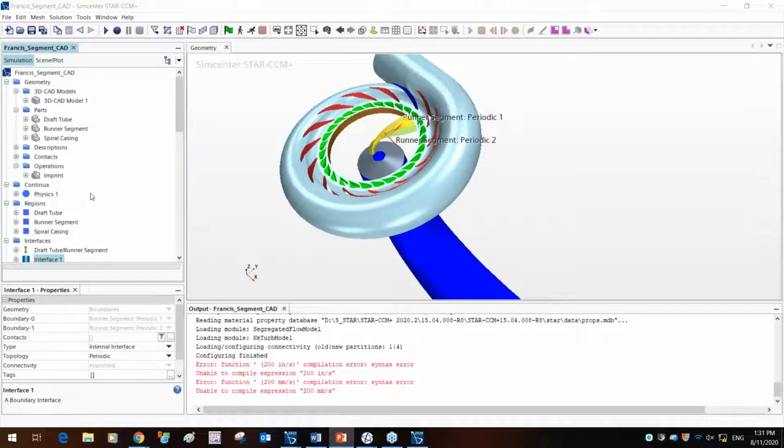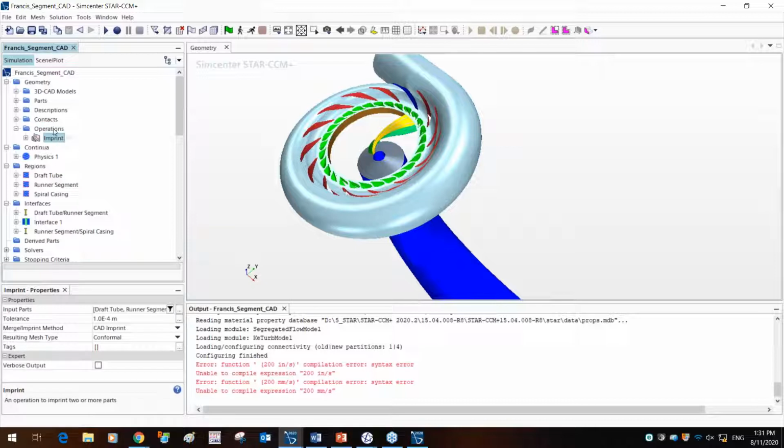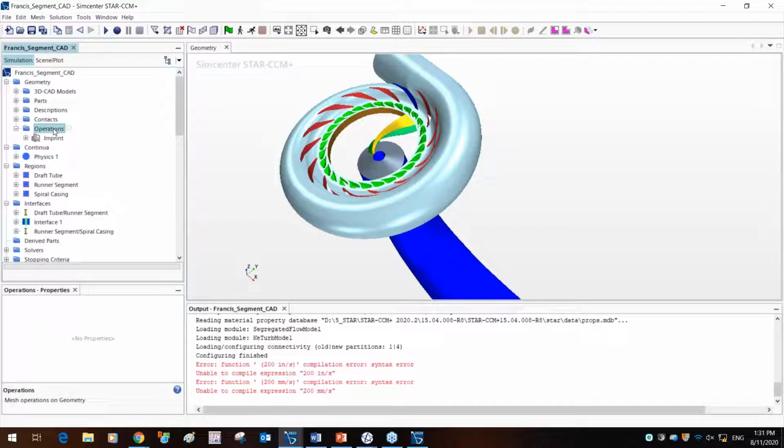So out here, as I mentioned earlier, the meshing process is in the operations. One of the key reasons is that any operation is conducted from top to bottom. So it's a series of operations where you can change which operation occurs first or second. Let's say one of the operations could be rotating the vane angle. You could create it as an operation, put a segment, then mesh it. Then any change to the geometry is run through that series of operations.